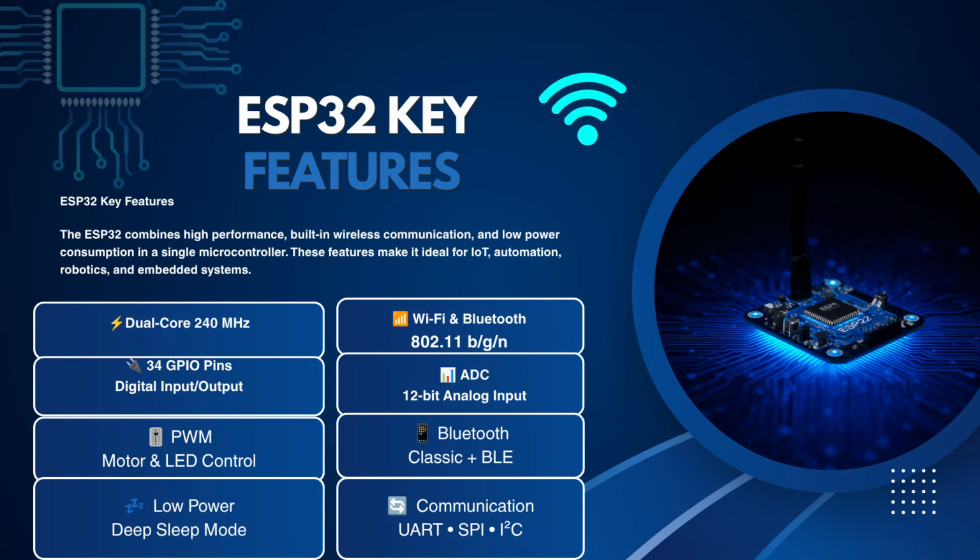The ESP32 provides up to 34 general-purpose input and output, or GPIO pins, which allow you to connect sensors, displays, relays, motors, and many other electronic devices. It also supports analog to digital conversion, digital to analog conversion, and pulse width modulation, enabling accurate sensor readings, analog signal generation, and motor control.